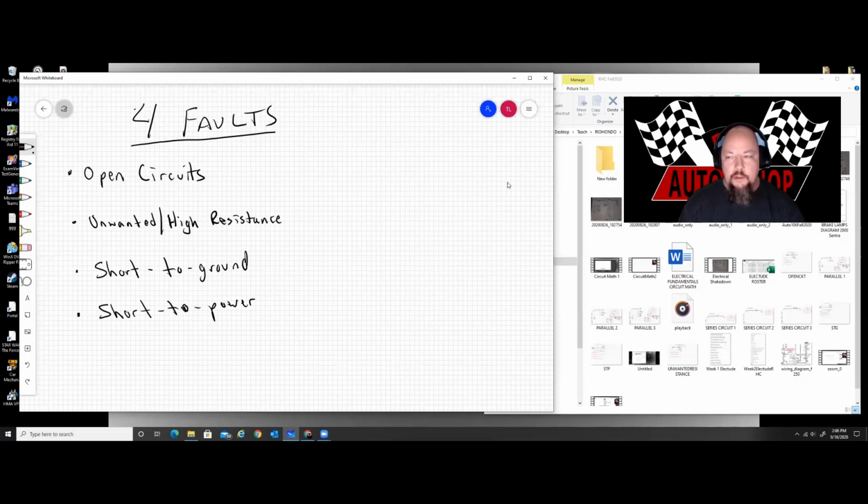Okay, I mean, some of these are exaggerated, mind you, but basically the wrong component's working when you activate a circuit. Now it means two hot wires have managed to touch, and the current is going to flow to the wrong circuit. It doesn't stop the original circuit from working. It's just both would be working when they shouldn't be.